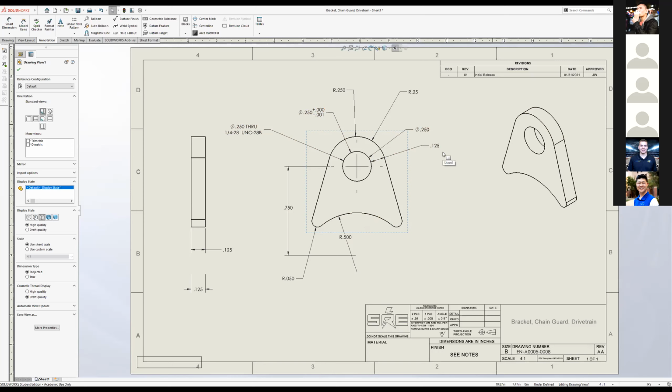And some suppliers, if we're going to give them a complicated part, the drawing definitely helps for holes and stuff, but the OD and everything should be, what do you call it? Critical. No, they call it, what's it called? Machine to CAD or something like that. Okay, reference to CAD. So they're going to use the CAD, put it in the software, and then use the drawing only for critical features. Yep.